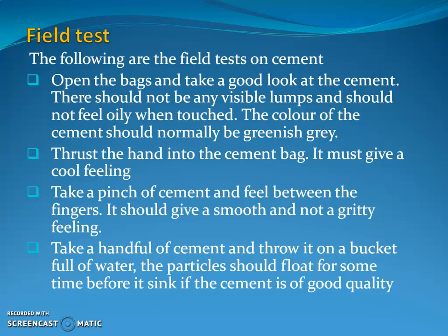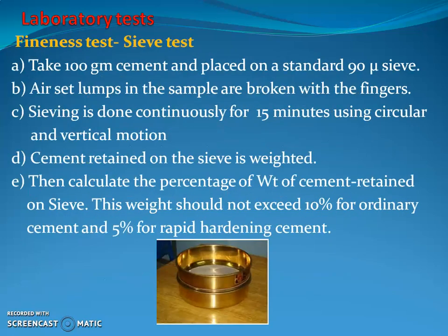Second one is to thrust the hand into the cement bag. It must give a cool feeling. Third one, take a pinch of cement and rub it between the fingers. It should give a smooth and not a gritty feeling. Fourth one, take a handful of cement and throw it into a bucket full of water. If the particles float for some time before they sink, then the cement is of good quality.